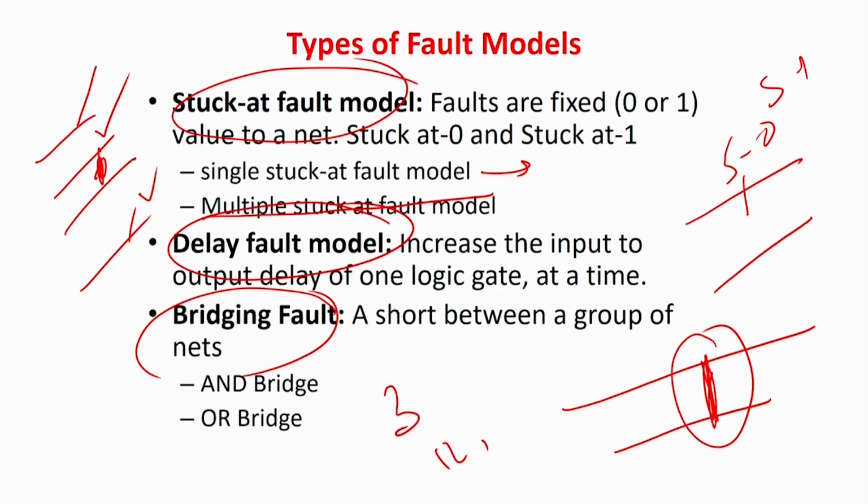So, what is the idea of a fault model? Basically, you do not even test the functionality of the gate, you just verify that the faults which are given in a list are not present in the circuit. If you are able to do that, then your testing is done.